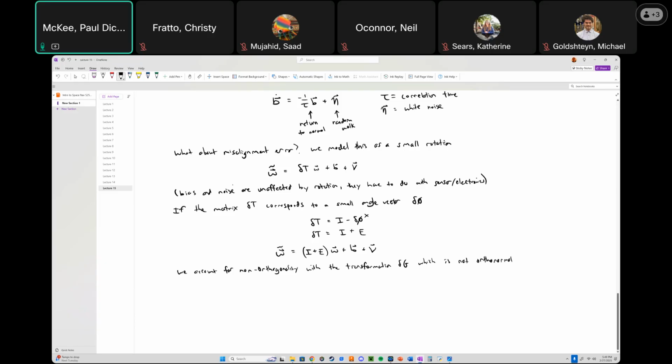So this is not a direction cosine matrix, because a direction cosine matrix is going to have a determinant of 1. It's going to have a norm of 1. It's going to be something that only rotates and does not scale, and it preserves orthogonality, right? We don't want that. We actually want something that causes this kind of shear, if you can imagine, so that all of a sudden your new x, y, and z unit vectors are not orthogonal to one another. So a pure direction cosine matrix won't accomplish that.